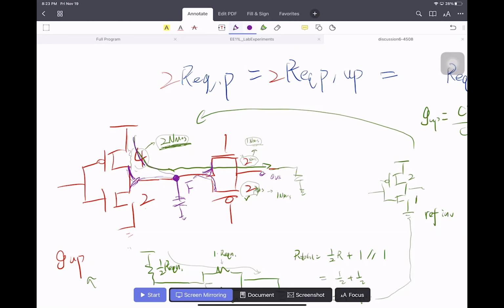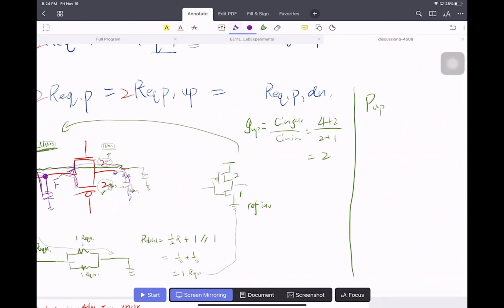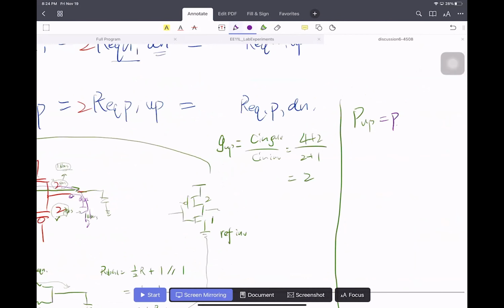So for the first stage, the inverter, if you regard this as a resistor, it will charge this node F capacitor first, and then charge the output capacitor afterwards. So there are 2 parts of the delay, because of the parasitic capacitance. Similarly, for the parasitic delay, it's also 2 parts. One is the output part, the other is node F. So the output part is just as what we calculated before. That is equal to C parasitic output capacitance over C parasitic reference inverter.